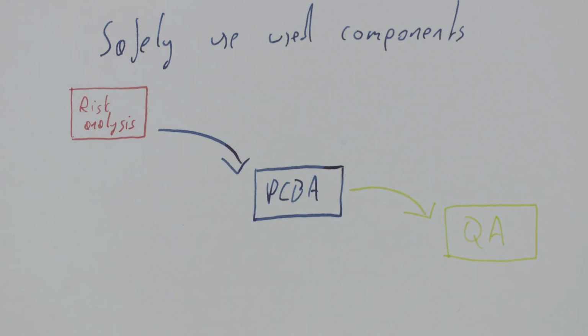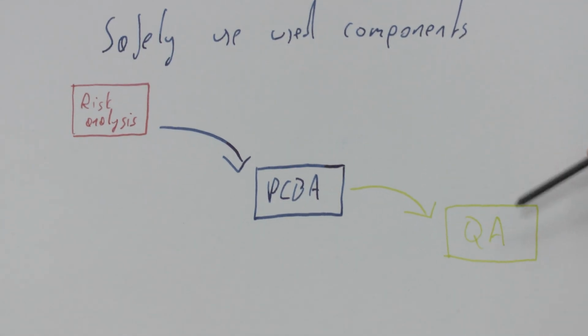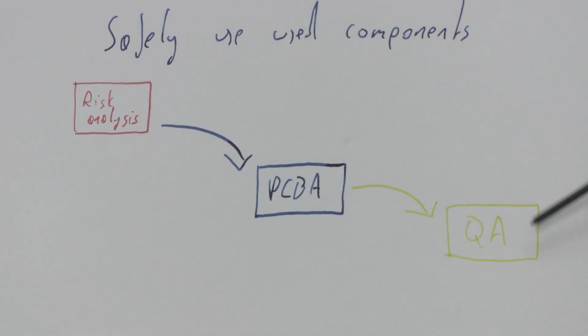You can also look into the datasheet a little bit and see what they say about reflowing and stuff to assess the risk. And secondarily, after the PCBA, you need to do a QA step, and this QA step needs to be done on site at the vendors, because otherwise you have these crazy shipping costs from the vendor to you and then back to the vendor. And for this, it can be helpful to create a special firmware which runs basically a set of tests and then says go or no go, so as to minimize the amount of time this step takes.